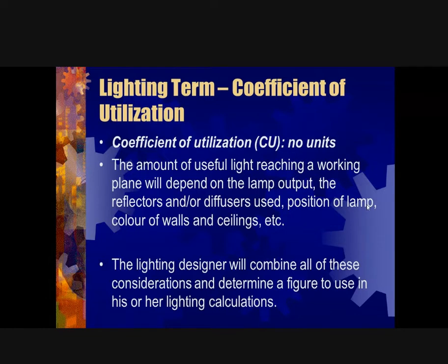Now, when designing, you as a designer of the light will have to determine the utilization factor based on the space that you're doing your calculations for. Typically, persons that don't know the calculation tend to use a rule of thumb in terms of positioning the lights.